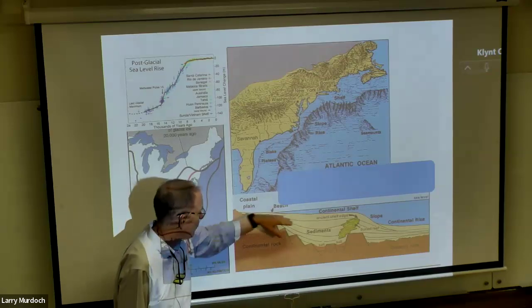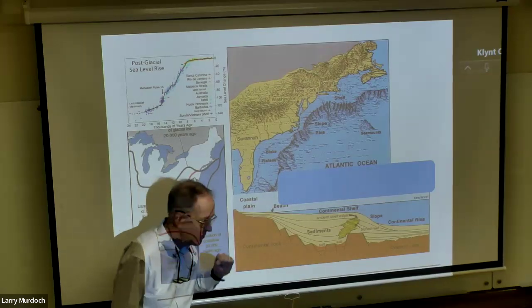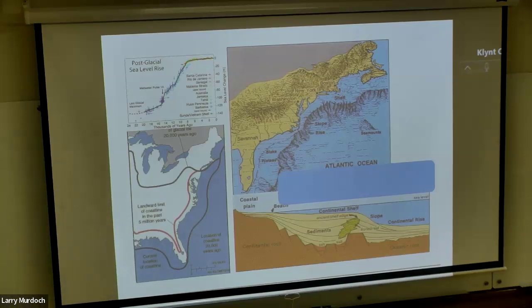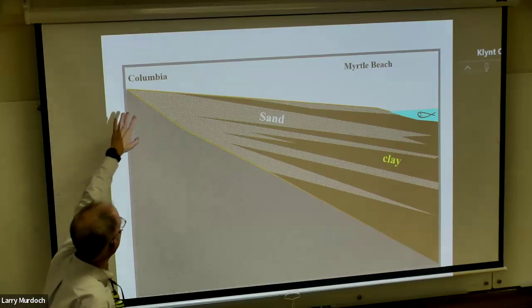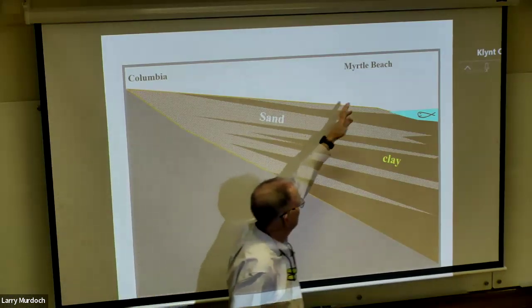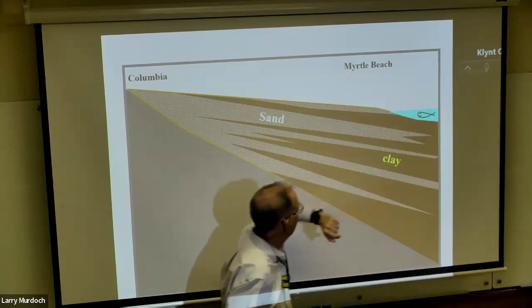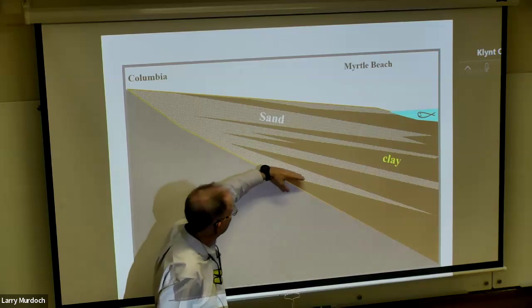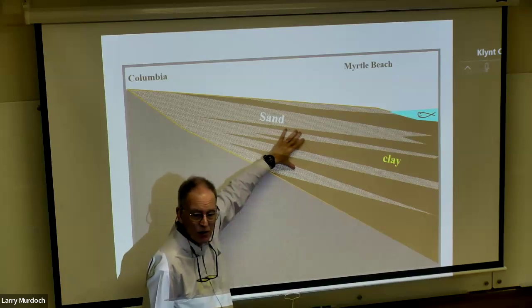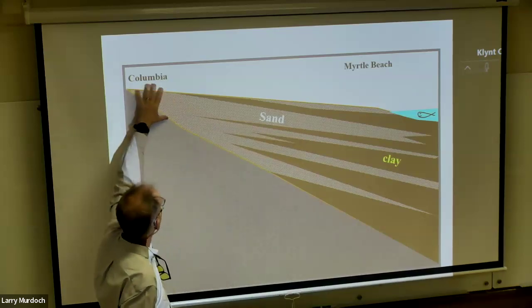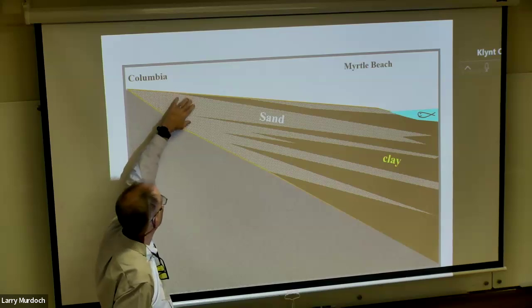and that forms very broad layers of interbedded sand, silts, and coals. So what that ends up with is creating something that is shown schematically here. So here's Columbia and Myrtle Beach and the ocean. And what we have here is maybe four-ish confined aquifers that are really thick here and really continuous.